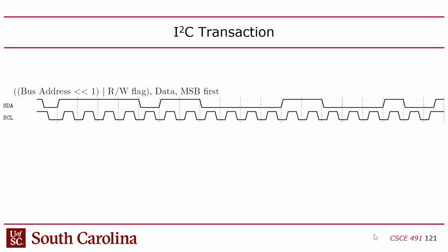So basically 1, 1, 1, 1, 0, 1, 1, 1, 1, 1, 0, 1, 1, 8 bits, right? And then there's the acknowledge. If I back up from the acknowledge, I think that's the read or write bit, if I counted correctly: 1, 2, 3, 4, 5, 6, 7, 8, yeah, the eighth bit. And that's a 0, which means write. The data is 0 there, so this is a write transaction.